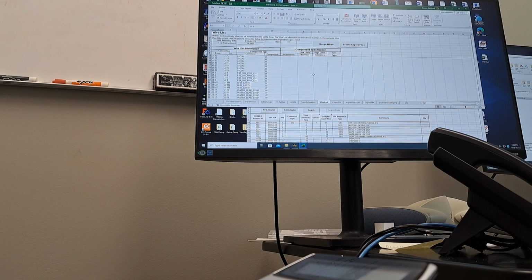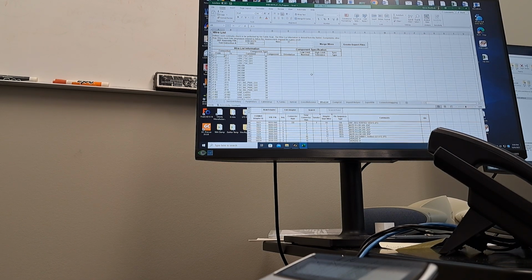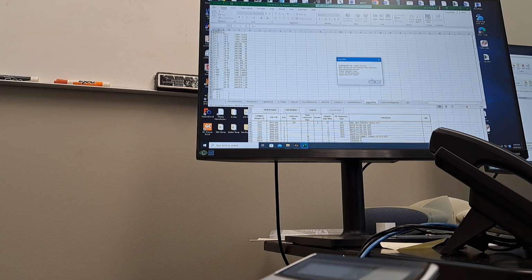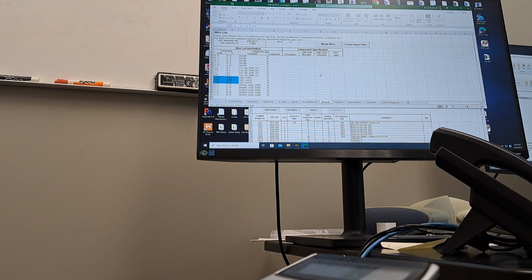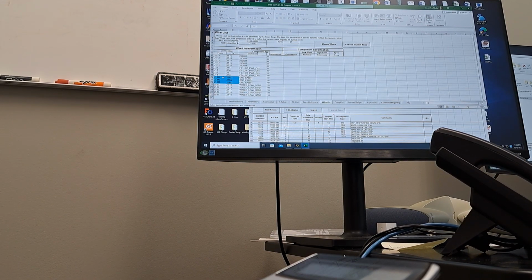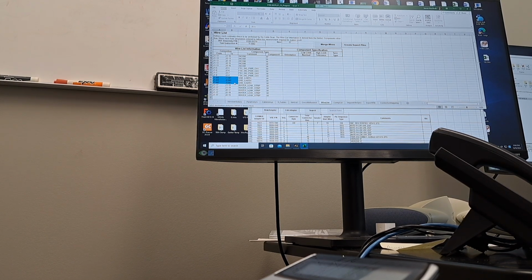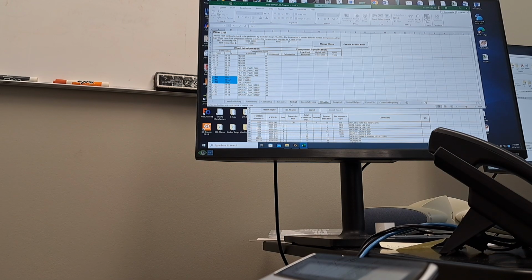Okay, so now it's still not perfect. We say create export file. It says I still have problems. These three: there's no M1 or M2 pins on J1. So here it's kind of up to you if you want to find them.